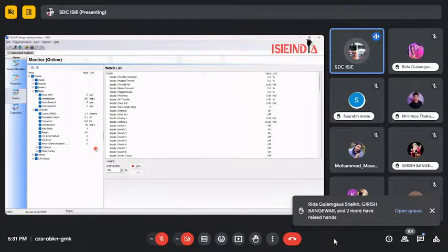So now I am showing you the connection configurations of some of the monitoring of the motor and controller only. In the motor, during deceleration, or when we have not given any throttle, we are getting 0 RPM, and the temperature limit is set up to 200 degrees Celsius. If the motor reaches 200 degrees Celsius or near about 165 degrees Celsius, the motor is going to be shut down. The power should be shut down through the controller, and the interlocking system is going to be on.